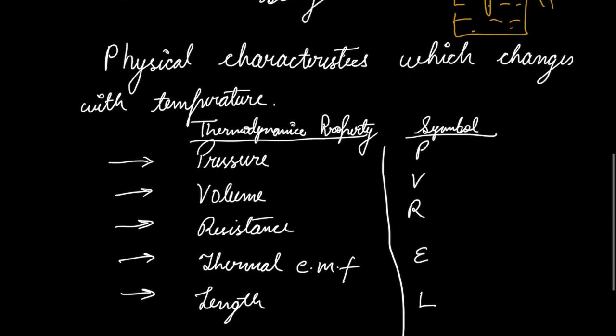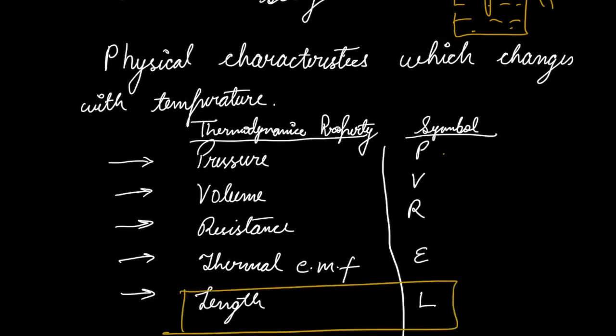Now, a few different methods are used for temperature measurement, and this broadly classifies all the different methods right now. You have to take a physical characteristic, a thermodynamic property, and see if it is changing with the change in temperature. One device could be, as we discussed, the mercury-based thermometer. That is length, or these are also called capillary temperature measurement devices because there is a capillary action going on.